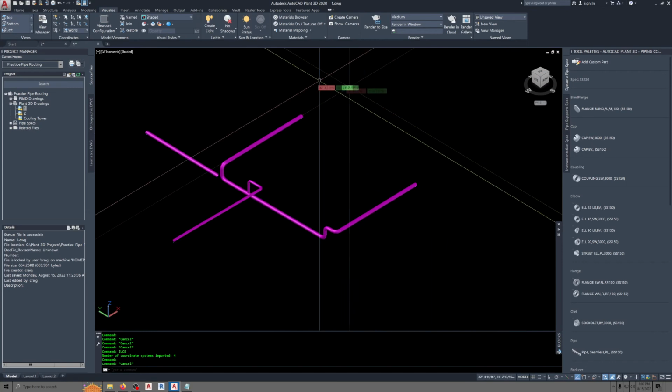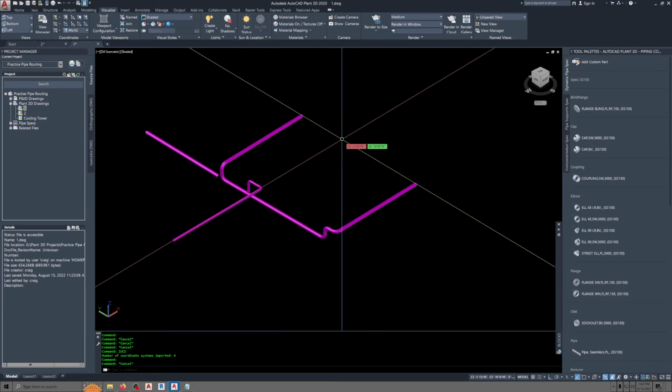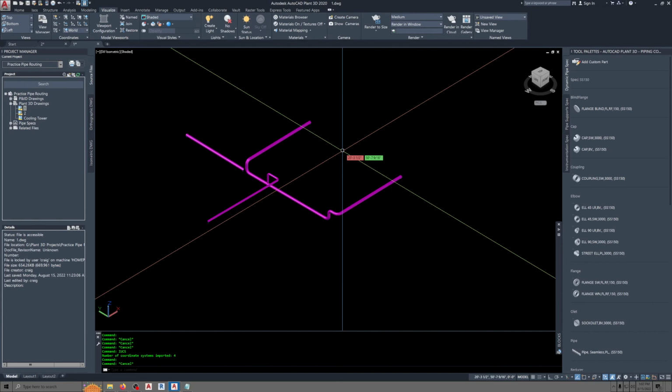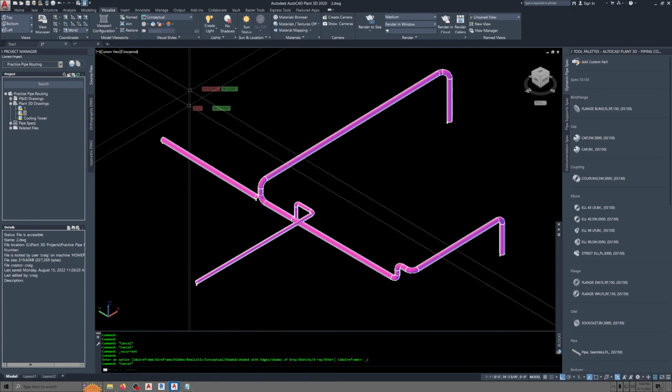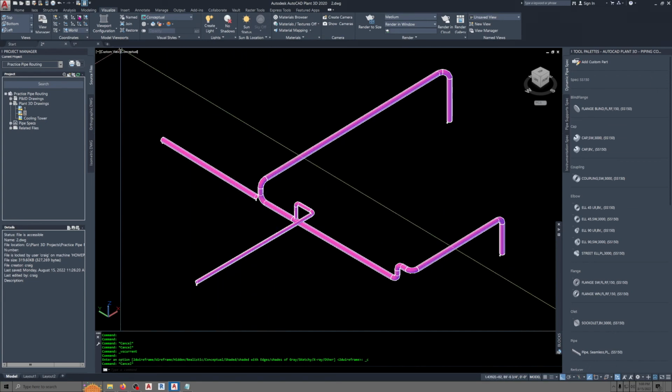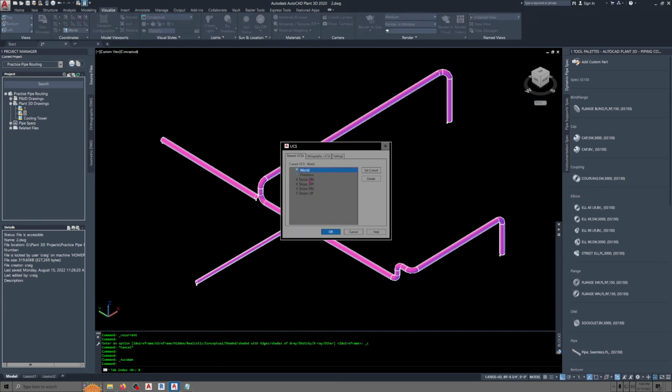If I were in charge, I would have that set up as a separate drawing file called user coordinate system sloped pipe or something like that. Put it on the network so it can be accessed by everybody. Anyway, that's step 1 in modeling sloped pipe. We'll have fun. One thing that I forgot to mention, if you don't like what you came up for names, you can go up here and open that up, and you can delete these or rename them and start over.